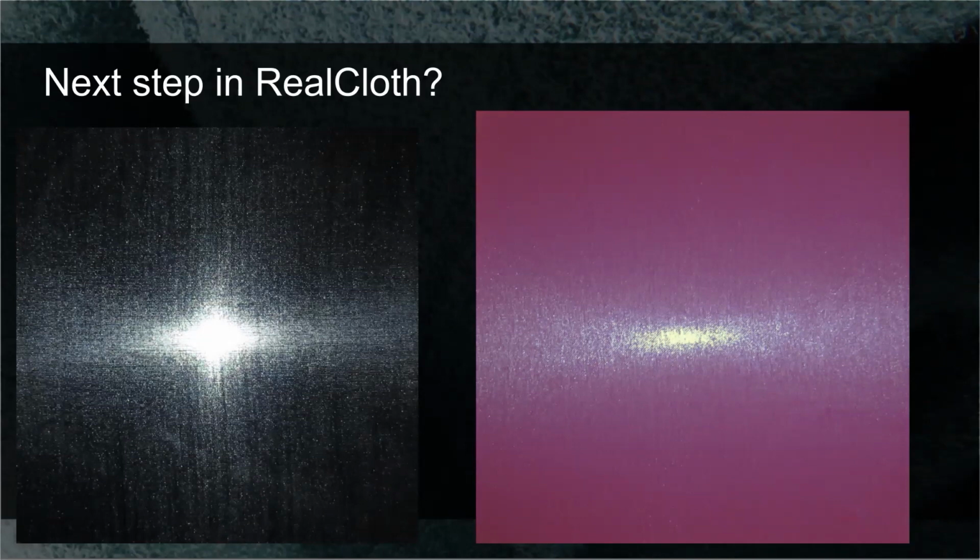So on the right, you have a more satin-like or silk-like behavior. So you get these very thin, straight lines and these ribbon-like yarns that tend to really favor one direction very strongly. And in the left-hand side, you see something that's more close to a plain weave, where both directions are more or less equally important, but because there are still two very important directions, the up and down and the left and right, you get this cross shape for the transmission.